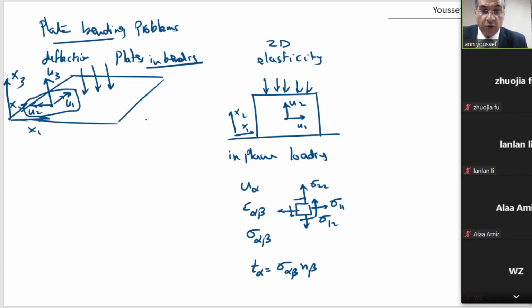That means this double arrow, I'm going to use the right hand rule. This rotation means rotation like this. Okay? So in order to be able to resist this rotation, we place reinforcement bars, steel bars, in this direction.